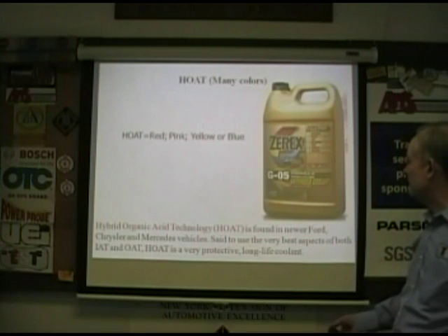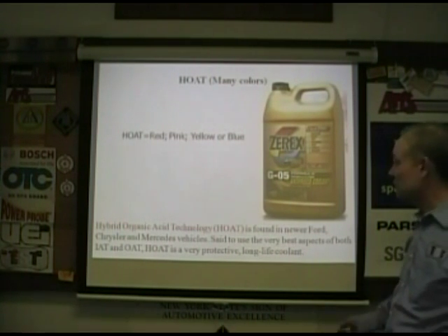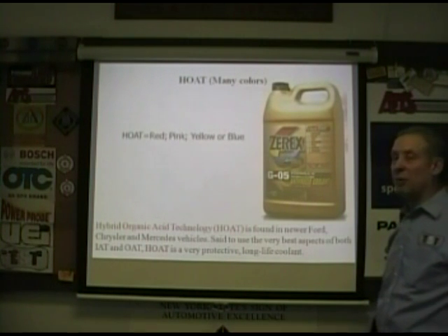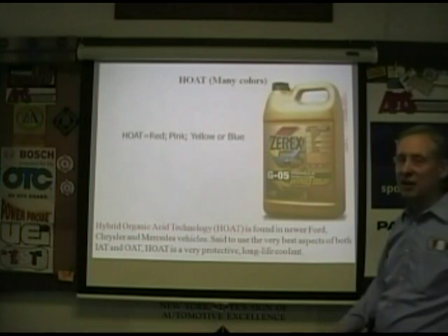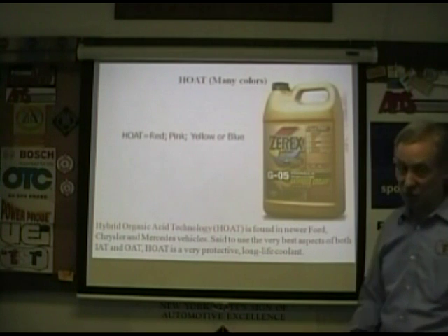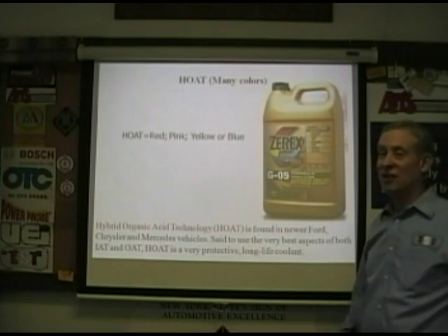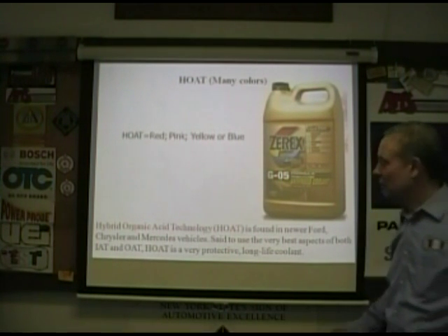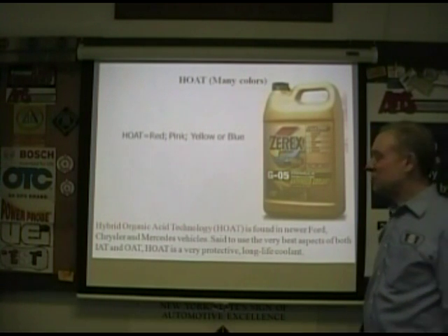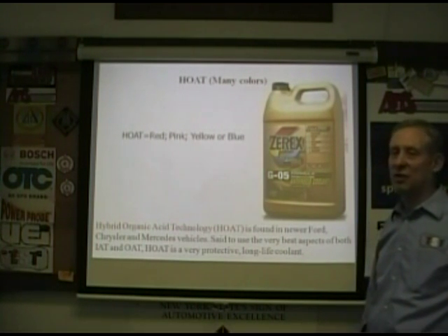The bottom line is it's found in a lot of newer vehicles. You see here Ford, Chrysler, Mercedes. It's supposed to combine the best aspects of IAT and OAT, and I'm sure it does. They want to give you this lifetime, don't ever change it thing. Again, I disagree with that. Change the coolant. Put the customer on a schedule.